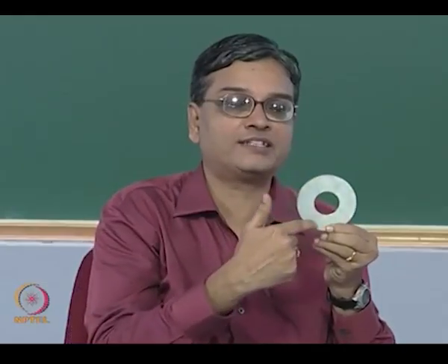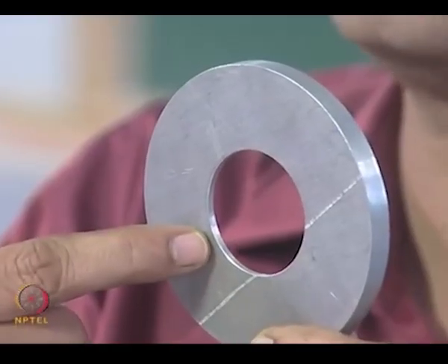Suppose I cut this horizontally, I have only a specimen like this which is open, like a C specimen, then I cannot take a circular contour like this, I will have to take a different type of contour. So, one of the tests is, if I am able to take an arbitrary contour and if I shrink it to 0, if I do not go out of the region, then that problem is simply connected, otherwise the domain is multiply connected. One simple thumb rule is, if I have cutouts like this, I have many cutouts like this, this is a multiply connected object.